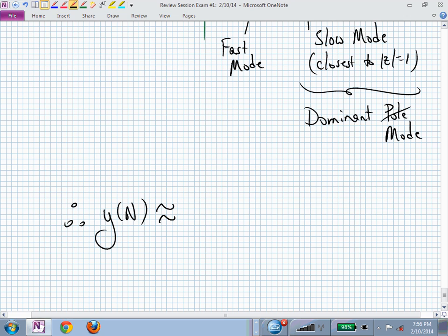We now say, okay, our big dominant pole has a radius of 0.9. That's our R. And so if we had a complex pole, we would find its magnitude. As long as it was inside the unit circle, we would use that biggest magnitude, and that would be our R value. Not the complex number, but the magnitude of that complex number. Is that clear?